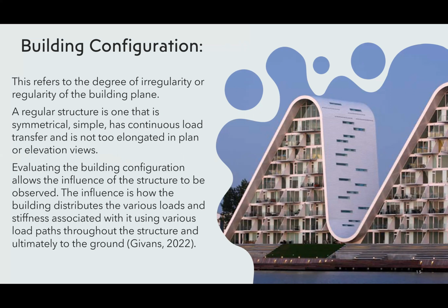For example, beams transfer roof loads to walls, floors, and columns. Columns transfer the beam loads to the foundation. Dead loads will be transferred from the roof or floor slab to the structural frame. But how they are positioned makes a difference. The greater the irregularity of a structure, the more detailed a structural analysis is required to reduce the impact of each irregularity.